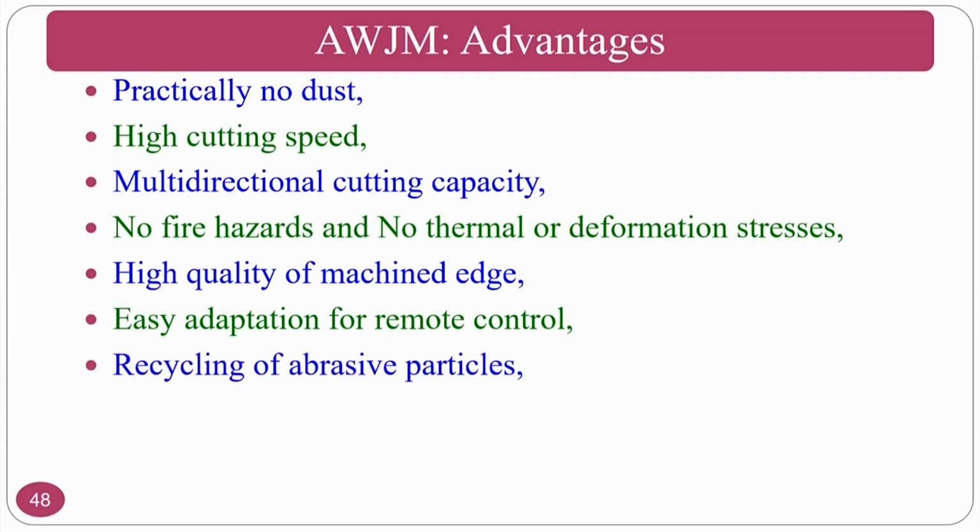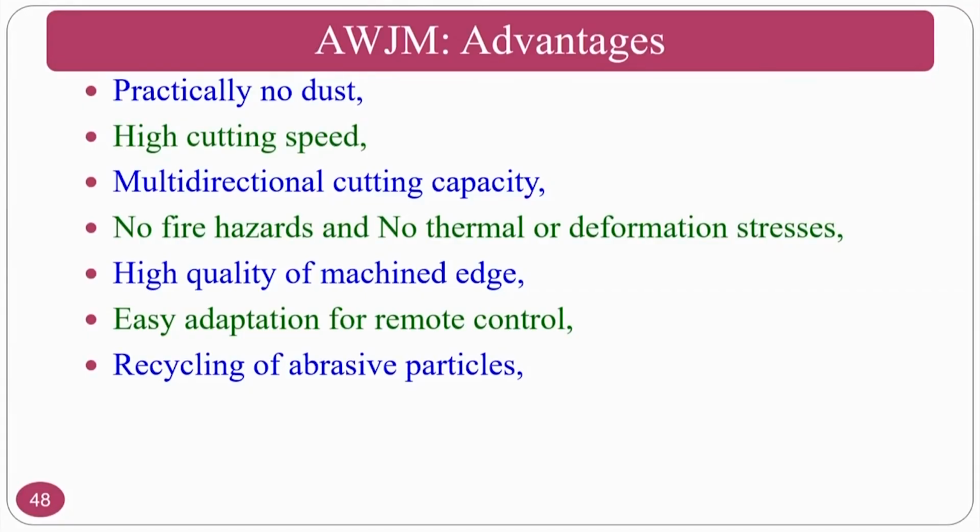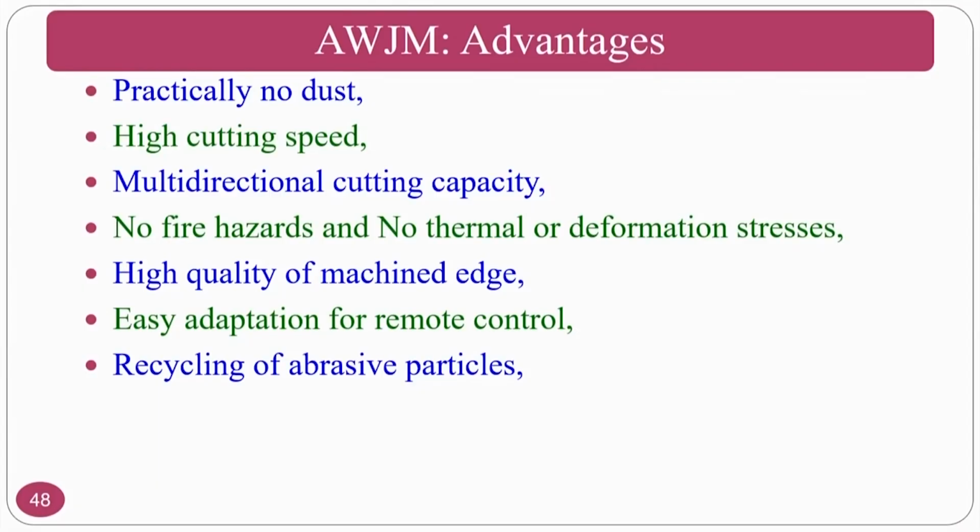Recycling of abrasive particles will always be possible, because there won't be adherence of workpiece chip material, because the water lubricates the abrasive particles as well as cools the workpiece material. So there won't be any high temperature generation or adherence of the workpiece material to the abrasive materials.